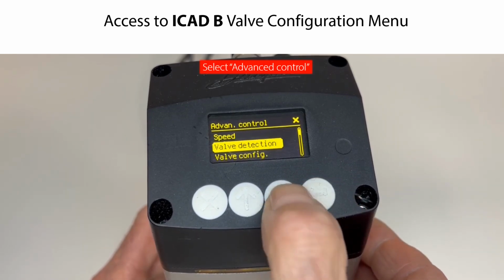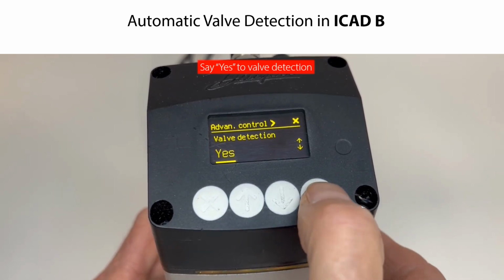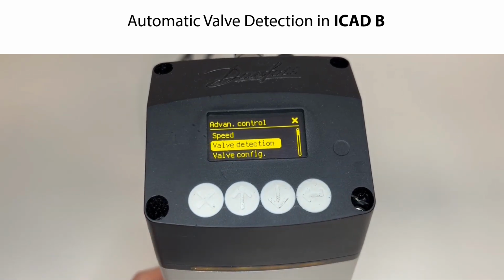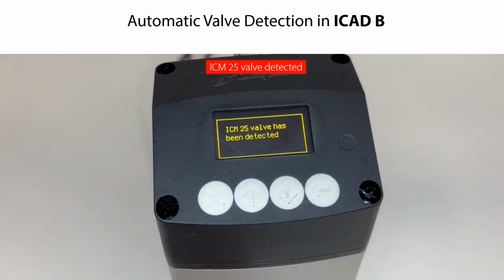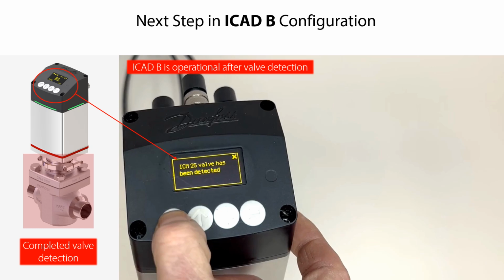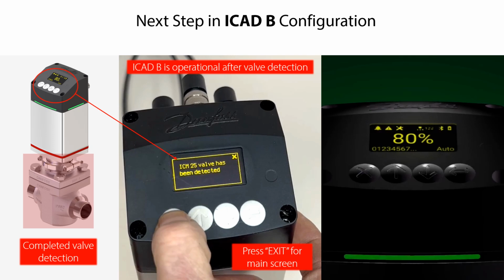Press enter. Then scroll down to Valve Detection. Then press enter. Say yes to the valve detection and then press enter twice. The ICAD B will now automatically detect and configure the valve onto which the ICAD B is mounted. As seen here, the ICAD B has detected and configured an ICM25 valve. After this valve detection, the ICAD B is now operational so that we can start exploring the navigation and parameter structures. Therefore, firstly press the exit key several times to return to the main screen.